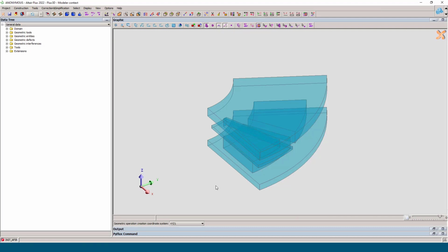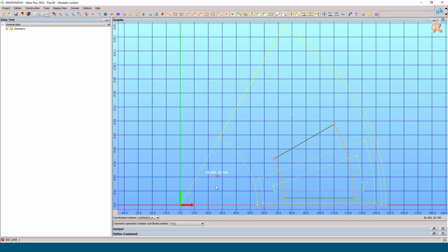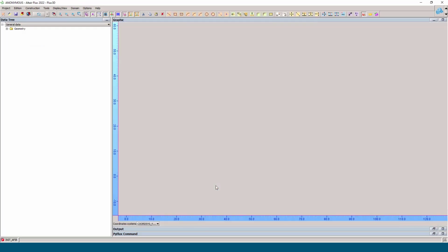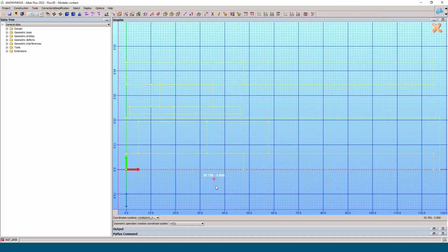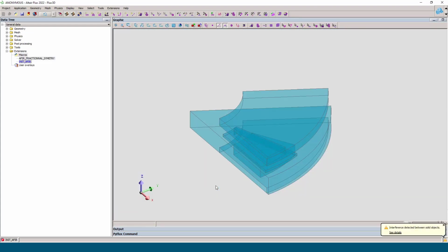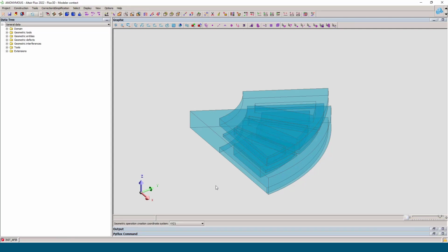Also, the portion of air around the rotor that allows us to define the rotation is built, similarly to the sliding line that we are used to using in 2D domain. The last geometry added is the infinite box to automatically apply the boundary condition to the model.